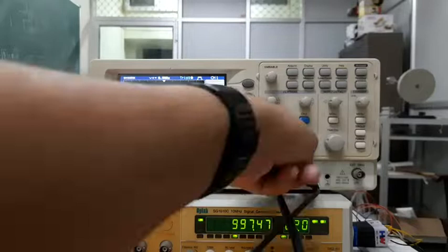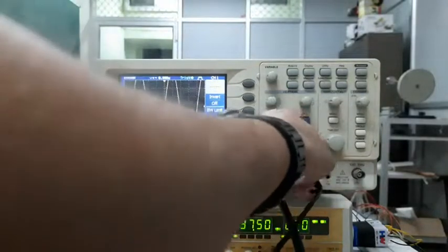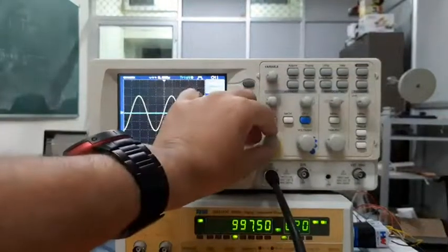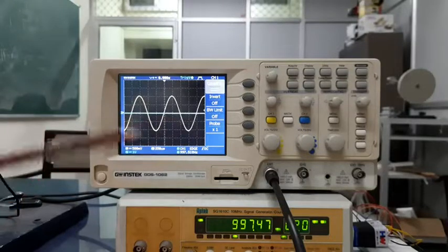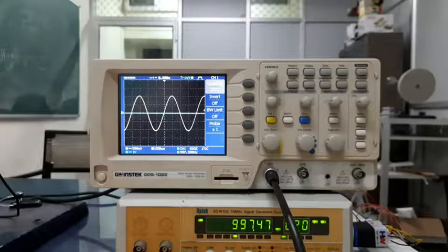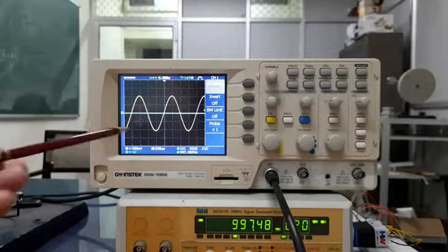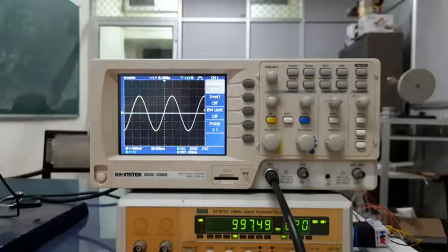Okay, anyway, we'll see this later on in actual circuits also, right? So that is more or less where we can start, looking at your oscilloscope. There are more things like measurement and other things, but I'll come to that later. Right now, when you see a signal here, for example, this is a signal. Suppose now I don't know what my input was and I'm given this output, I can still get an idea what this output is just by looking at and reading some things off the graduated scale. So it looks like a sinusoidal waveform, periodic. So it's a periodic sinusoidal wave.